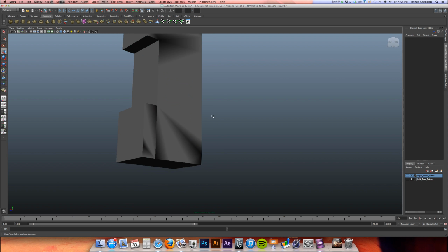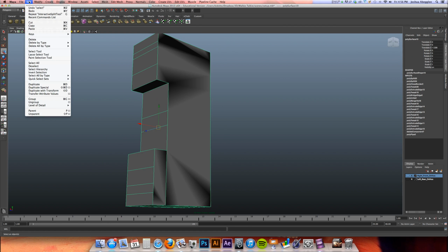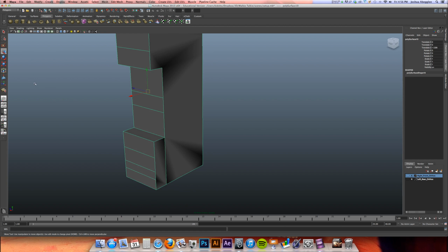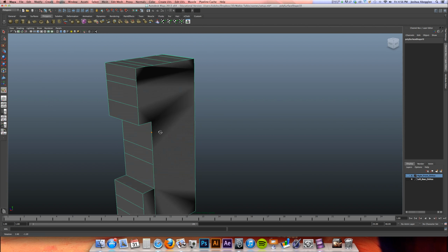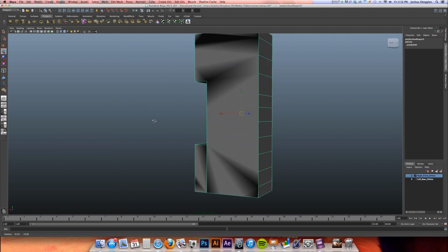Every once in a while, when something's not working the way it's supposed to, it's not a bad idea to come over to Edit, come down to Delete by Type, and delete your history, because there could possibly be something that exists in the history state that's getting in the way of this action that I'm attempting to perform. And sometimes Maya is just a turd.